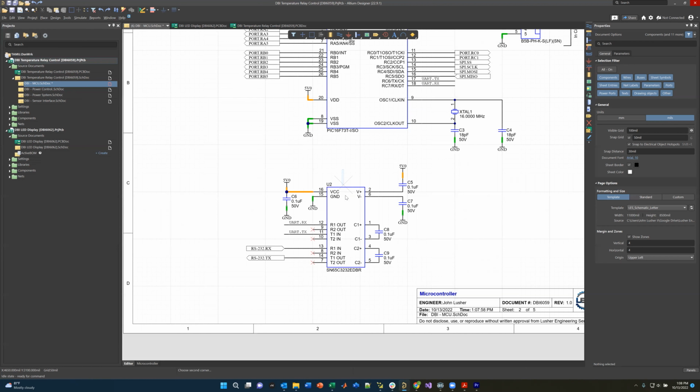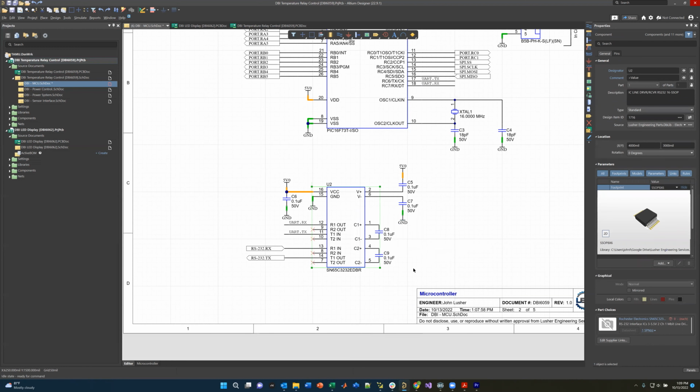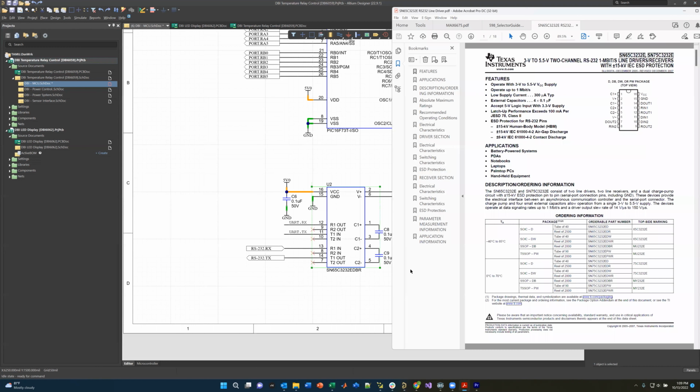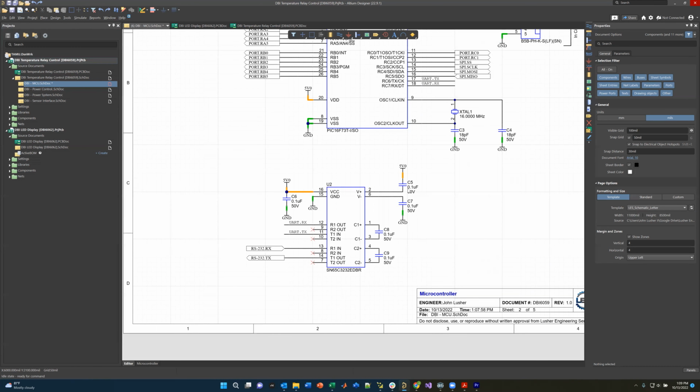So this device, a chip from Texas Instruments, actually produces the proper voltages. Instead of having to have a plus or minus 12 volt power supply, because you don't see plus or minus 12 volts here, it uses what's known as a switched capacitor DC to DC converter. It takes these 4 capacitors and internally builds the plus or minus 12 volts it needs to do RS-232.